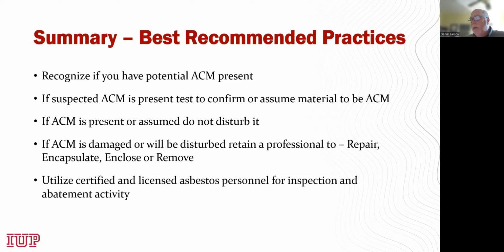If the asbestos containing material is damaged or it's going to be disturbed, you need to get a professional involved to choose a corrective action, a response action, which can be, of course, to repair, encapsulate, enclose, or remove it. And again, for any type of work like that, whether it's inspection activity or abatement activity, you want to get certified, licensed asbestos personnel involved to help you make the right decisions.